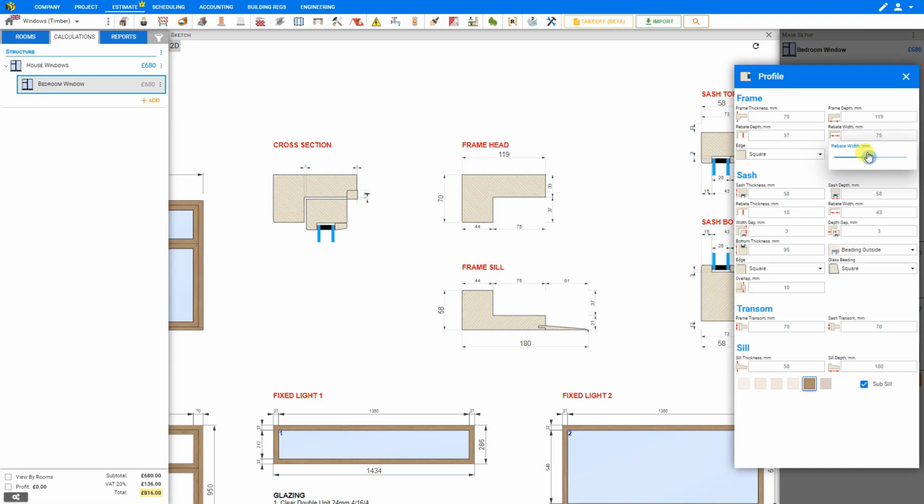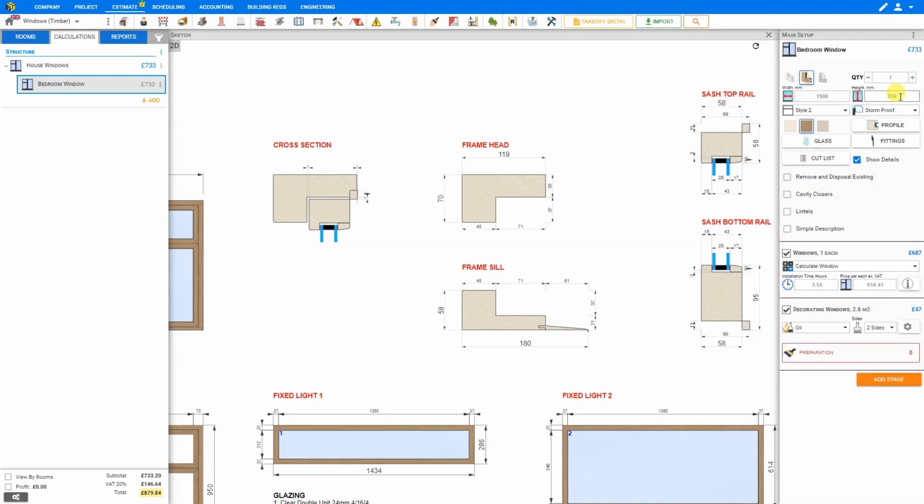If we want our casement to be fully flush, we recommend closing this window and changing the setting here in the main stage from stormproof to flush casement. And you'll see that here in the sketch. We'll return this to stormproof so that we can see all the extra cutouts and rebates.